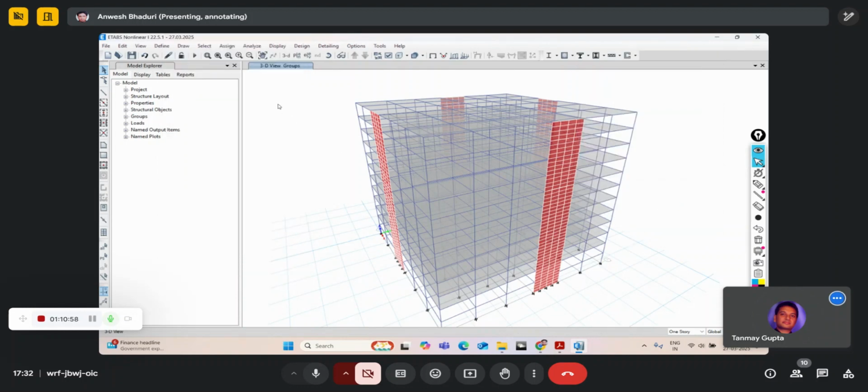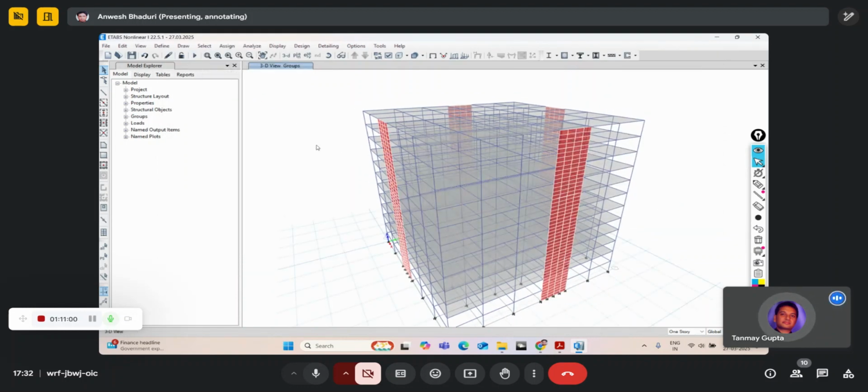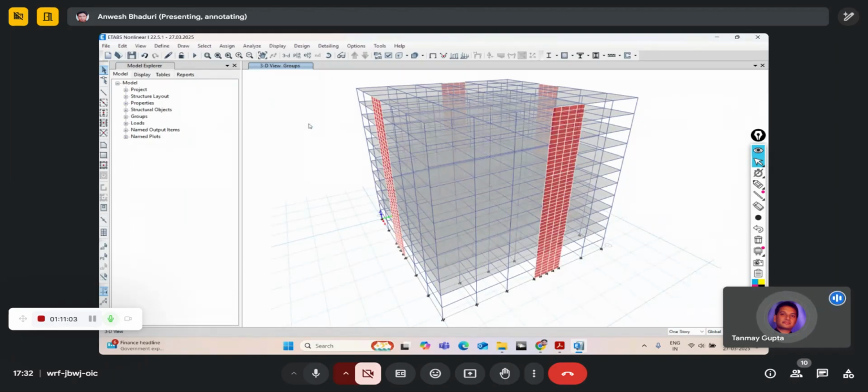Groups are useful as a faster selection method. If you select a group, you can do faster selection of that particular entity. It's very useful when you work with, let's say, multiple trusses, where the web members need to be selected separately and the top chord needs to be selected separately, when there are different sections.